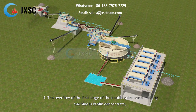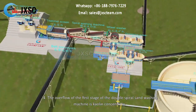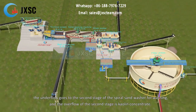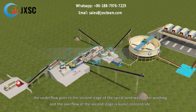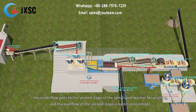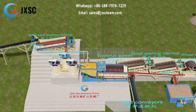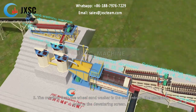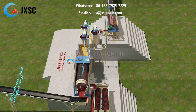4. The overflow of the first stage of the double spiral sand washing machine is kaolin concentrate. The underflow goes to the second stage of the spiral sand washer for washing. And the overflow of the second stage is kaolin concentrate. The underflow goes to the wheel sand washer. 5. The overflow from the wheel sand washer is the concentrate. The underflow goes to the dewatering screen.